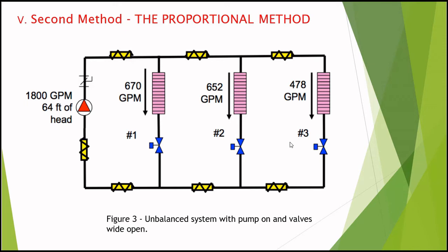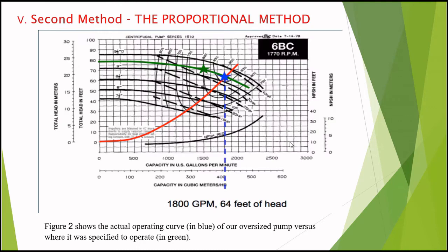So what to do to solve this issue? And why are we getting these numbers? We can see this is the system curve, and this is the pump curve, the selected pump curve. Our design parameters, our selection or best efficiency point for the pump, is here, 1500 GPM at 70 feet head.